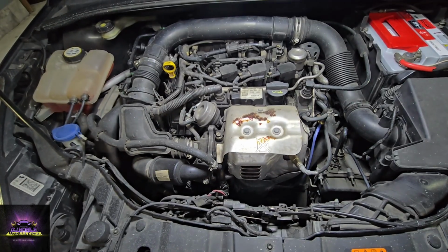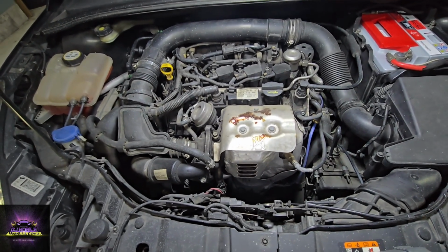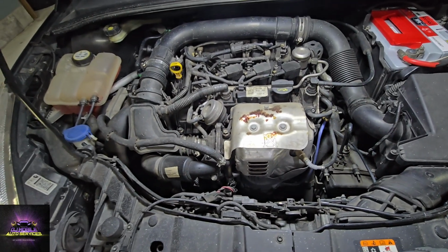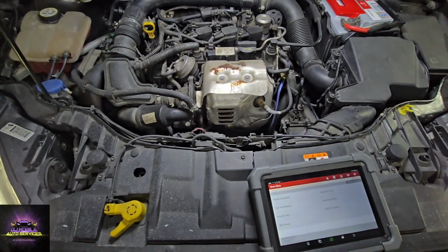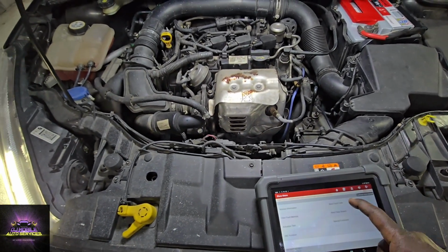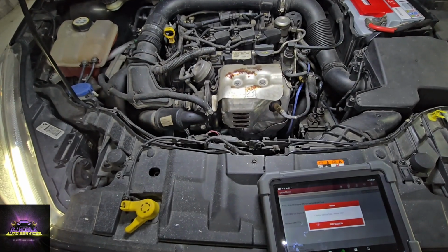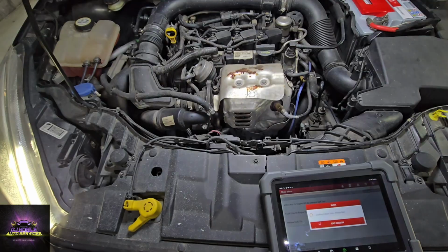But let's see exactly what's going on. As I said, I gotta get my tools on this throttle to see if we could get some sort of direction. Is it the ECU? Is it the throttle? Is it a harness problem? So I removed all 4 codes from the system. Let's rescan the vehicle and see if we get that P2112 code that returned for the throttle actuator. Let's see what's going on.